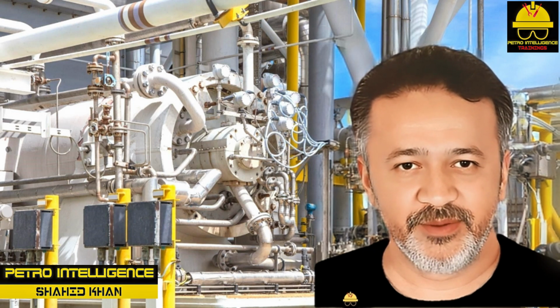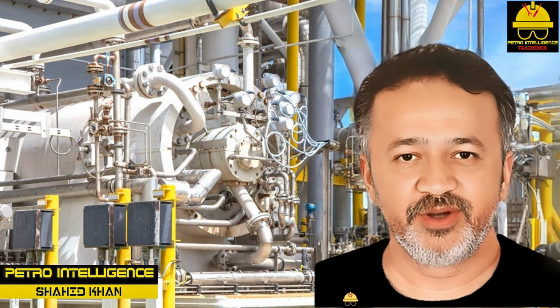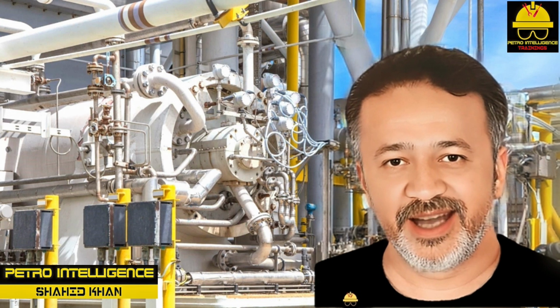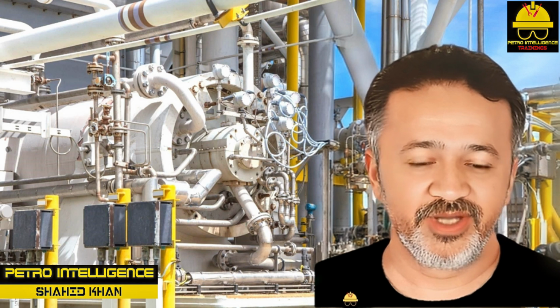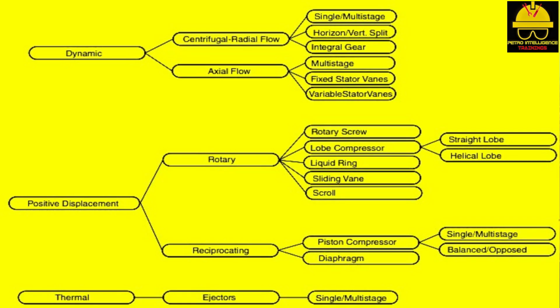In a refinery or chemical plant, compressors are used to compress gases such as light hydrocarbons, nitrogen, hydrogen, carbon dioxide, and chlorine. These gases are sent to headers, from which they are distributed to a variety of applications. There are 3 basic designs for compressors as shown in picture: dynamic, positive displacement, and thermal. Dynamic compressors include centrifugal or radial flow and axial, straight-line, flow compressors. Positive displacement compressors include rotary and reciprocating compressors.